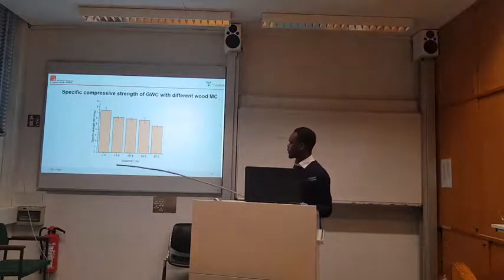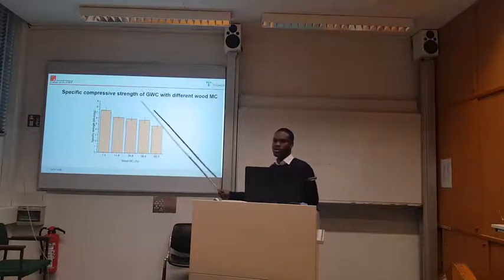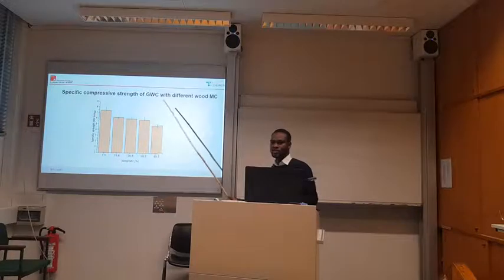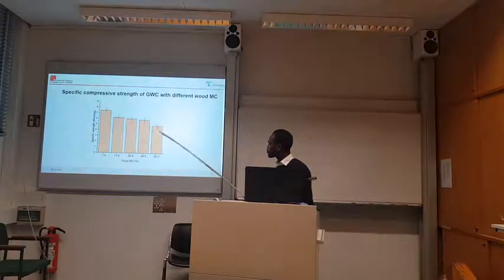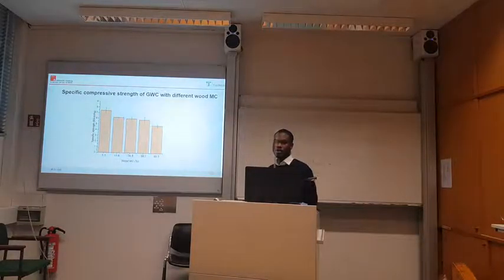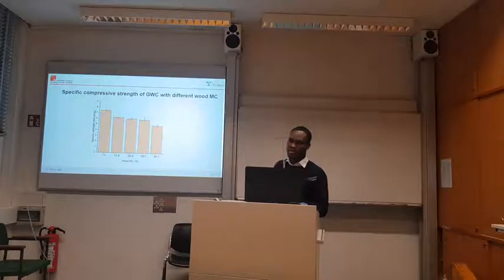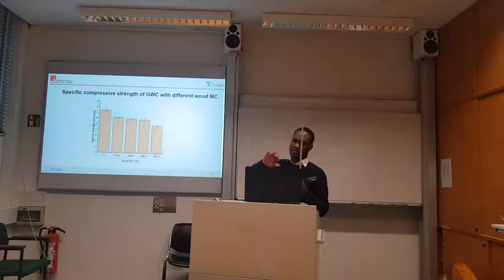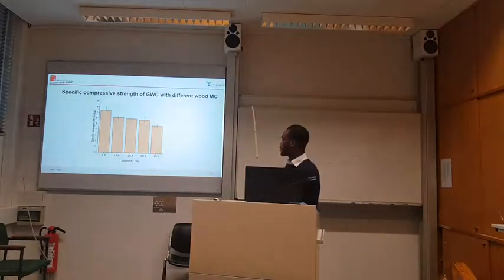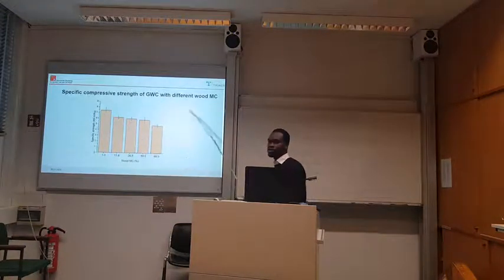This is the specific strength, so the strength divided by the density. So the issue of density has been cancelled out. But once the water comes out, definitely you are creating pores, because the water has to get out through some pores, so it creates its own channels, and you are reducing the strength of the material because there are more pores. Now there is also a bit of less compatibility between the surface of the wood and the material. So the specific strength also reduces with increasing moisture.